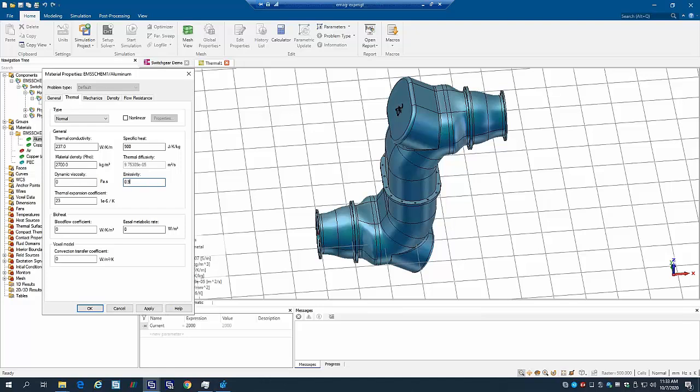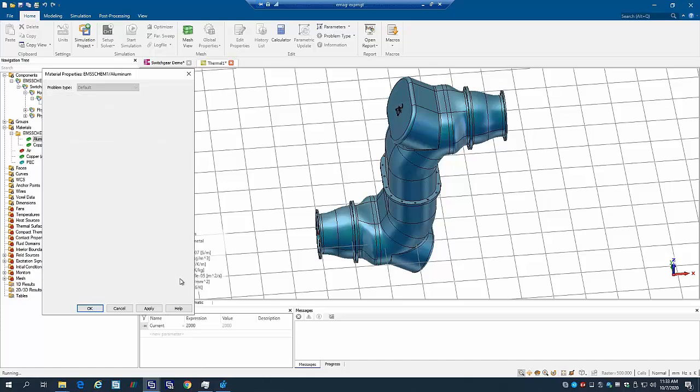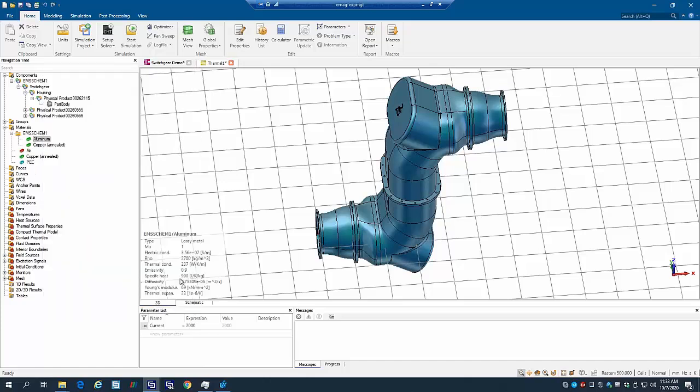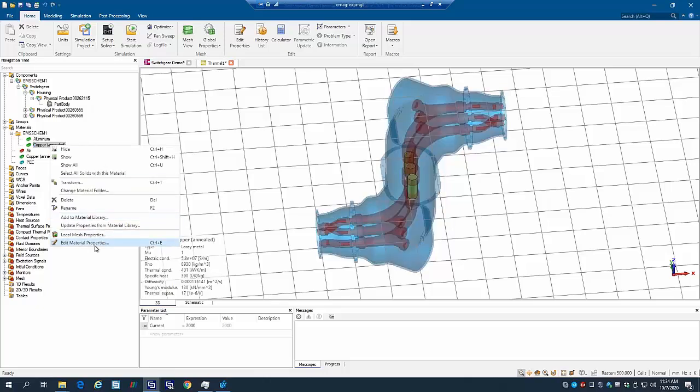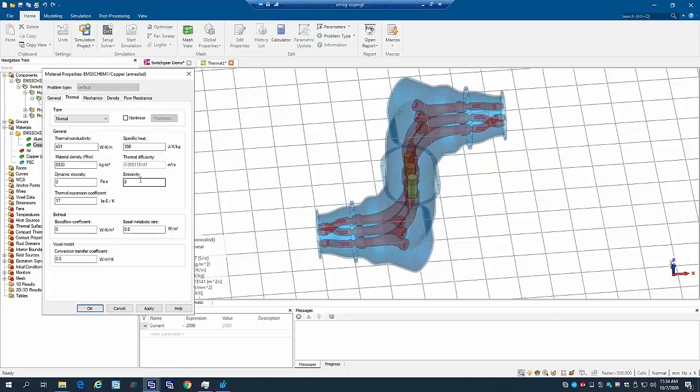called emissivity. Emissivity is a number between 0 and 1. It calibrates the surface, whether it's a really good reflective mirror-like surface, which is almost 0, or it's a black surface, which is 1. So usually the material, to take advantage of radiation, you would design it with higher emissivity to radiate more than the mirror. You don't want to polish it to a mirror-like situation. And if there's some copper inside, I can change this to a better emissivity as well. That's all you have to do.